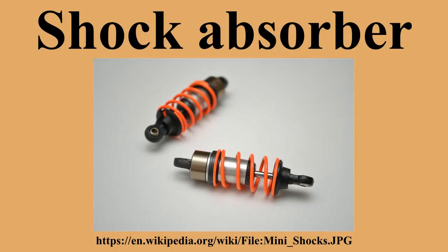Inertial resistance to acceleration. For example, prior to 1966, the Citroën 2CV had shock absorbers that damp wheel bounce with no external moving parts. These consisted of a spring-mounted 3.5 kg iron weight inside a vertical cylinder, similar to, yet much smaller than, versions of the tuned mass dampers used on tall buildings.